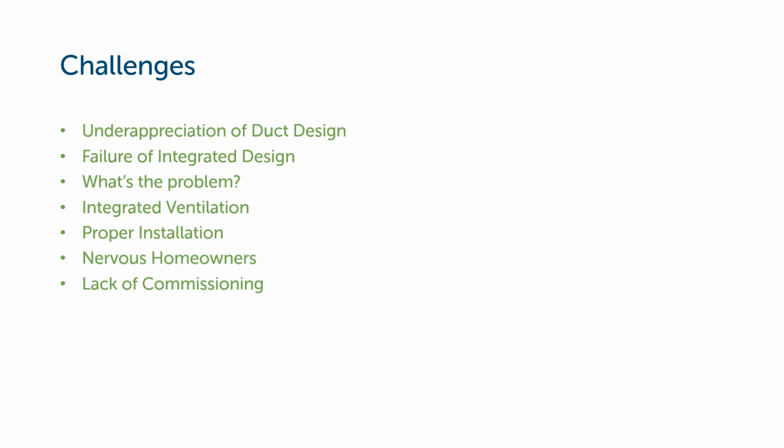Nervous homeowners. A colleague of mine was just telling me a story about a duct design done by a very well-respected engineering group. They designed a great duct system that was really appropriate for the super low-load home. And then when the ducts started going in, the homeowners were pointing at the duct systems, going, "That's too small. Those ducts aren't going to work." They were nervous because they didn't know that regular sized ducts would have been vastly oversized for their home that needed 500 CFM.